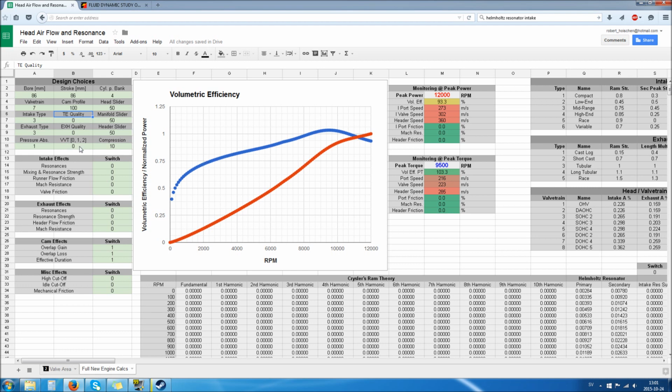But there is a magic trick, and that is called VVT. VVT adjusts the timing of the valves such that it minimizes overlap, or optimizes overlap, for the lower revving engine, while it still allows the full overlap to occur high up where it's optimized for, and even a bit beyond that. So what happens here is especially interesting for engines that kind of want to have a bit better economy rating down low, or a bit better torque curve. And if we put it to 2, then you see the overlap effect is reduced.